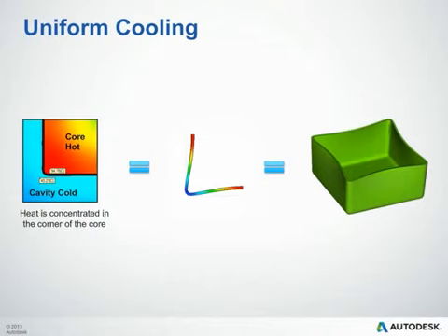As a result, the inside corner runs much warmer, allowing more time for the molecules to cool down and shrink, therefore collapsing the corner in a bit. This will essentially pull in the sides of the box towards the core, as you can see in this image on the far right. We commonly call this corner effects.